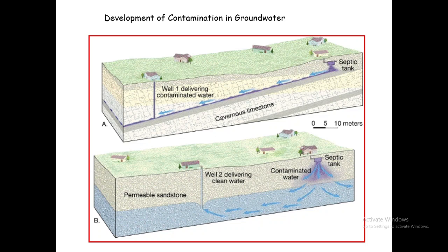So due to this percolation, due to the deeper soils, and furthermore due to the dilution, the role of this contamination has very much reduced. So it is very much dependent upon the geological features, geological formations, and geological structures which are existing beneath the contamination source, that how it is going to behave for the movement of contaminant along with the water or the pores.